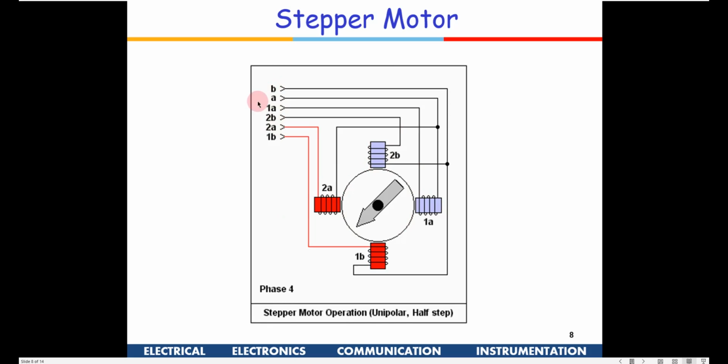So these can be digital inputs, and based on these digital inputs, I can make the rotation. The frequency of these bits will decide the frequency of rotation, and you can also give small variations in the digital signal. Accordingly, the rotor will go and stabilize in one position based on the digital input data. So this is one more application. These inputs can come from a counter, so you can do up counting or down counting to get this rotor to a specific desired location.